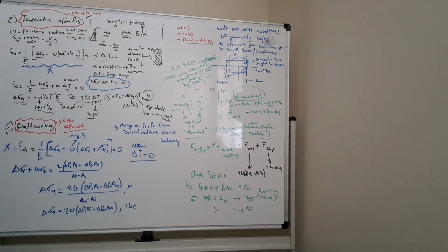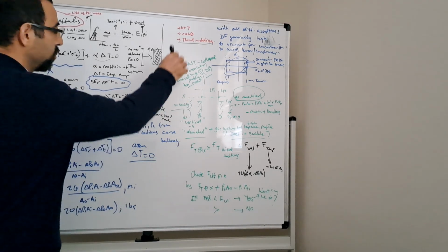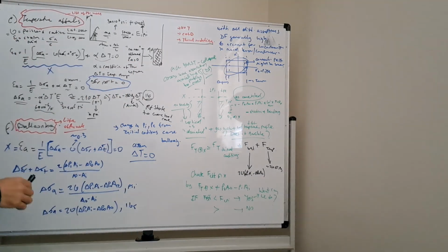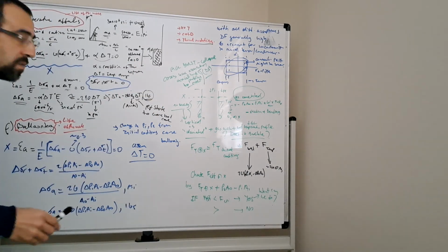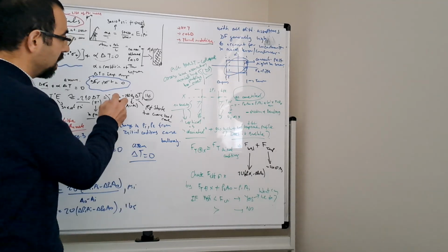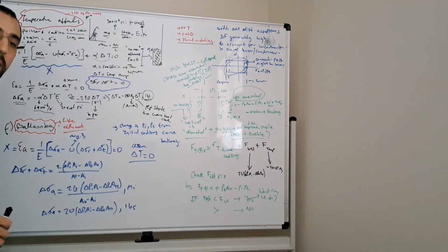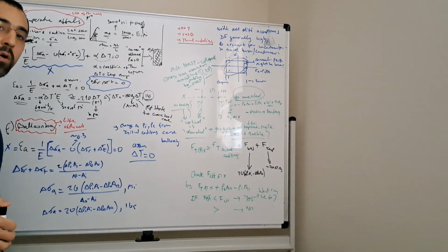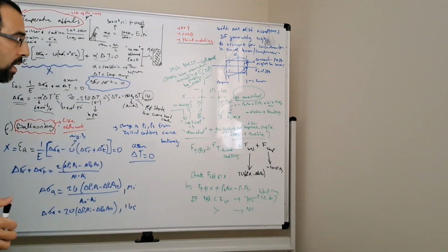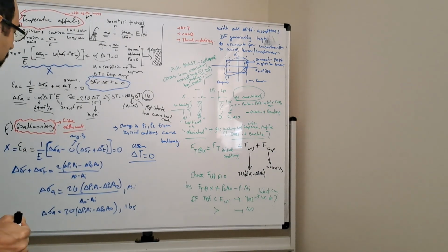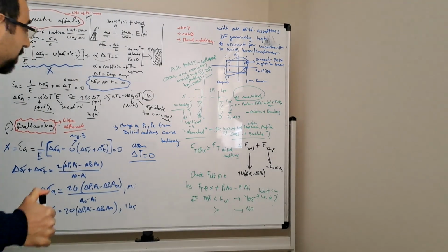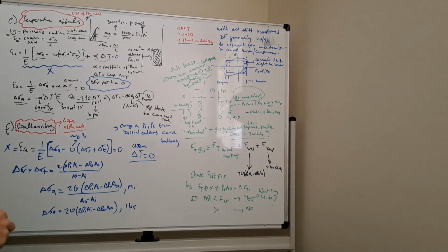I think if you look at some load cases of stimulation or hot case, especially for tubing, when you start producing the well and then you heat all the corresponding casings behind, this value can be quite high, and then it can basically draw your true tension profile quite low, and then have an impact on your effective tension or stress profile as well.